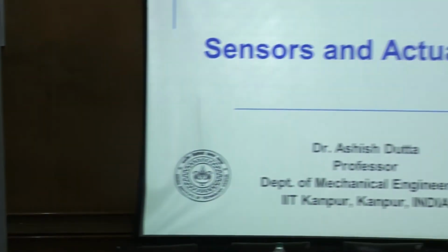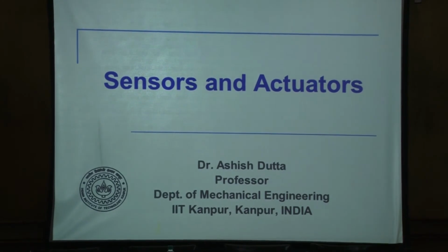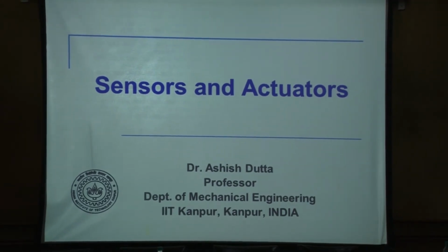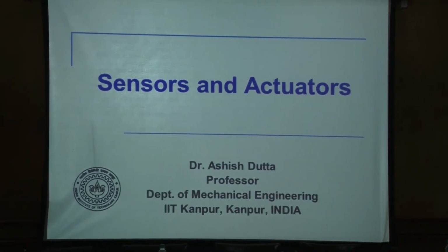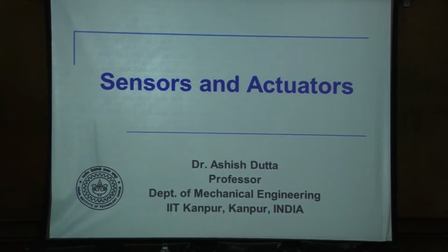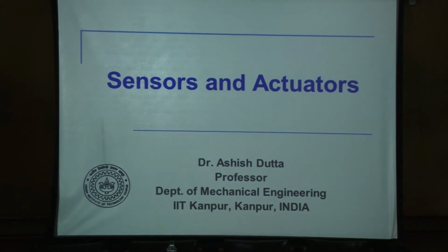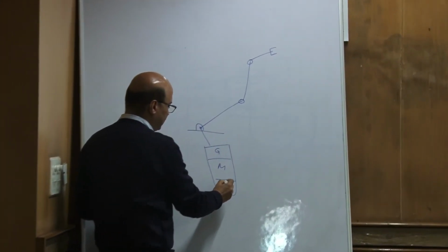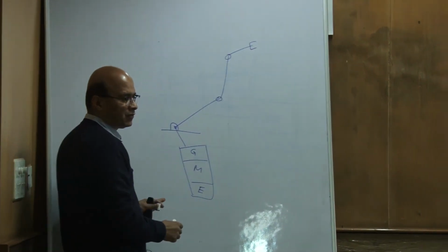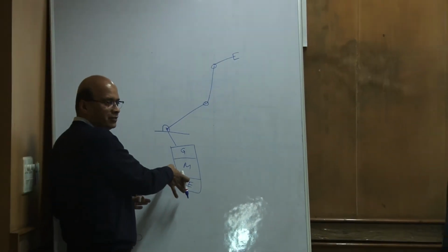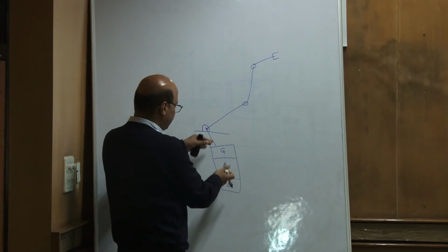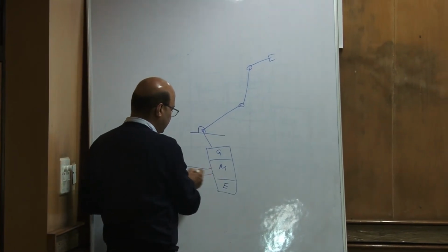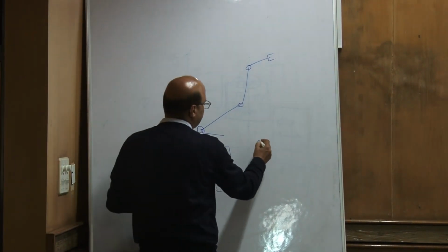The robots are actuated as follows: we have a joint, and each of these joints is connected with a motor, which is an actuator. There is a gear in front to increase the gear ratio, and there is a position sensor like an encoder at the back. Each of these comes as one compact unit, and this is called independent joint control.